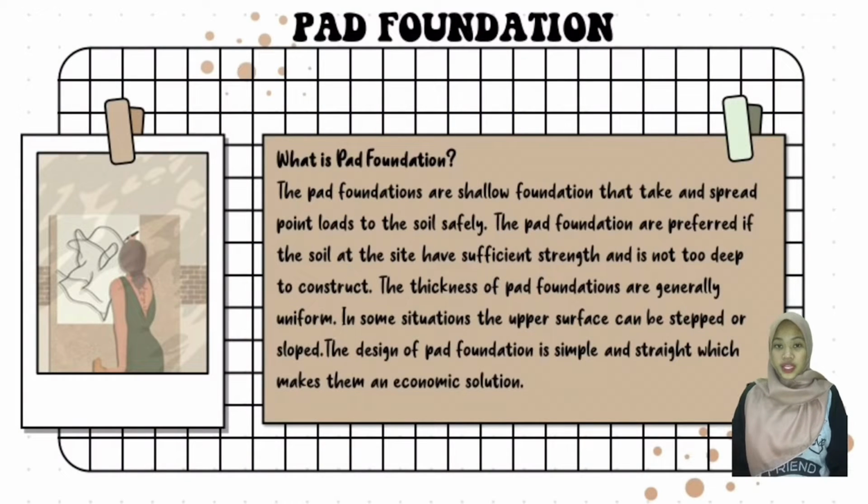What are pad foundations? Pad foundations are shallow foundations that take a wide spread load to the soil safely. Pad foundations are preferred if the soil at the site has sufficient strength and is not too deep to construct. The thickness of pad foundations is generally uniform. In some situations, the upper surface can be steep or sloped. The design of pad foundations is simple and straightforward, which makes them an economic solution.